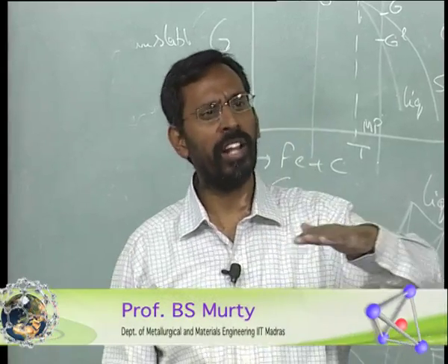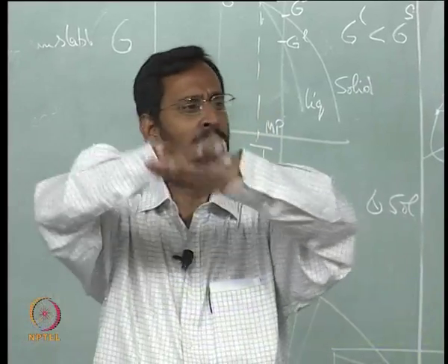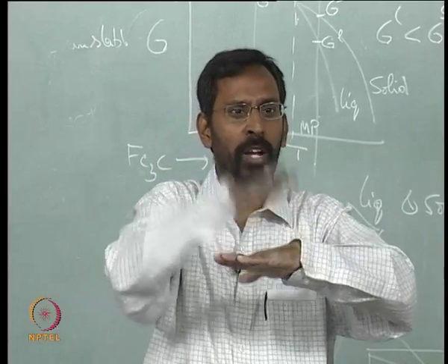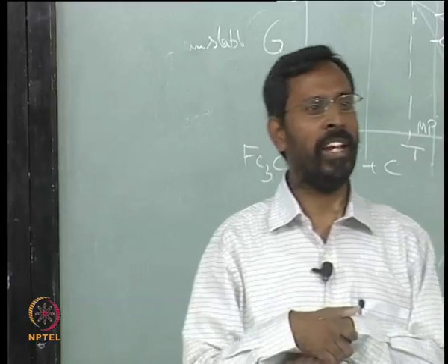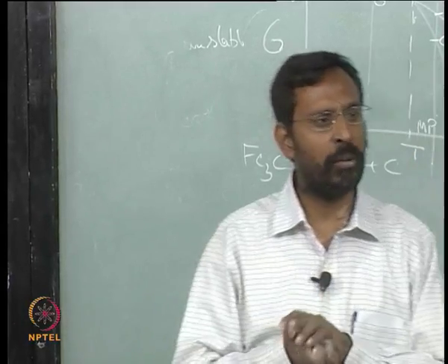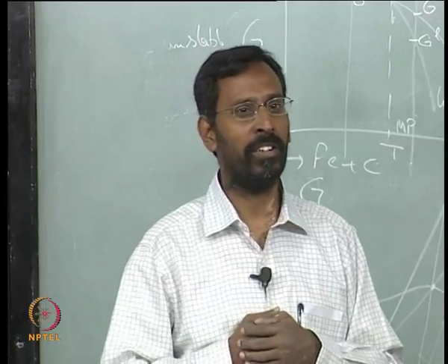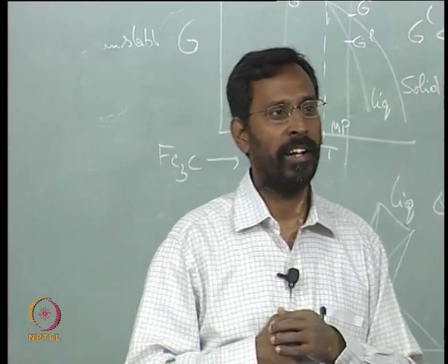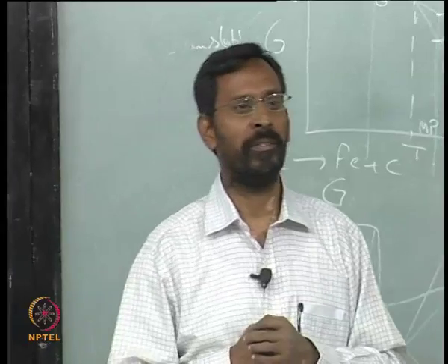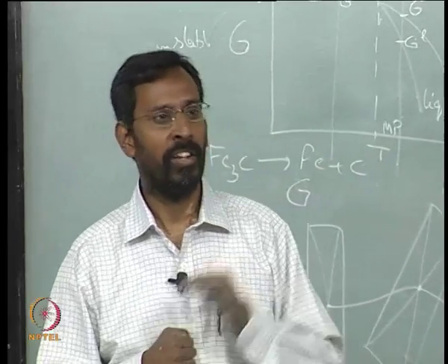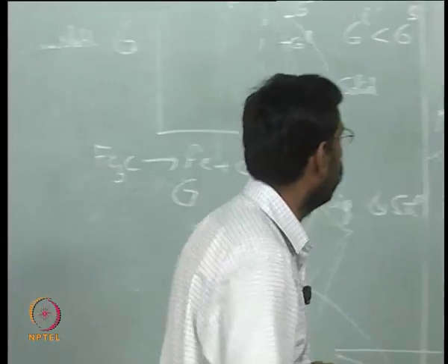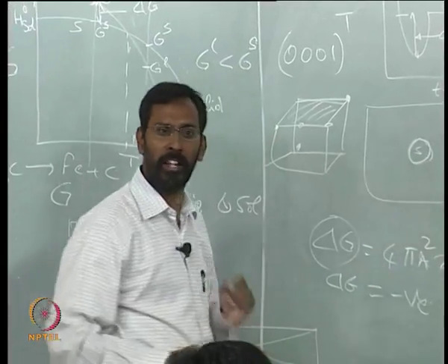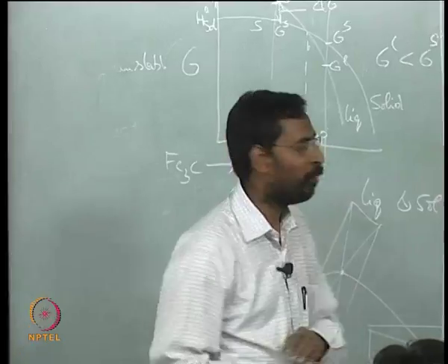Why I say this is that nucleation always occurs on a plane, it cannot occur anywhere, it happens on a surface, that is why the planes are important. There is a certain plane in HCP which is exactly similar to another plane in FCC. How much crystallography do you know? What is the closest packed plane in HCP? What are the indices of it? 0001. Okay, the 0001 plane is similar to another plane in FCC. Can you think of it? 111, perfect.